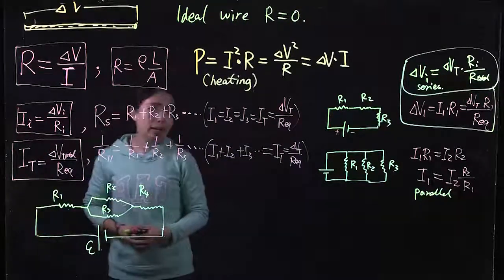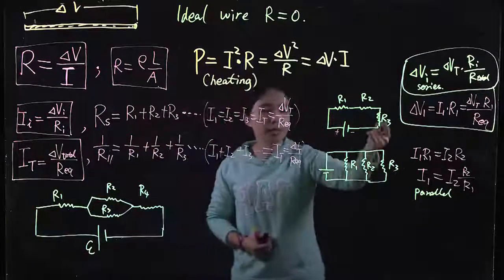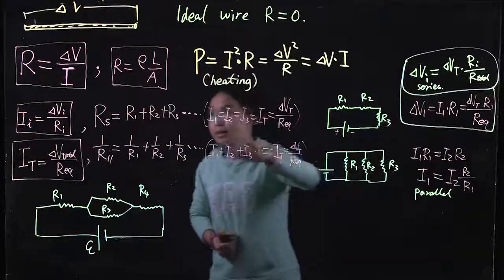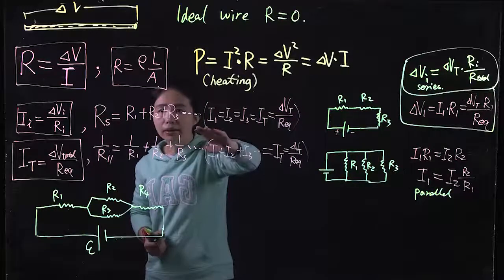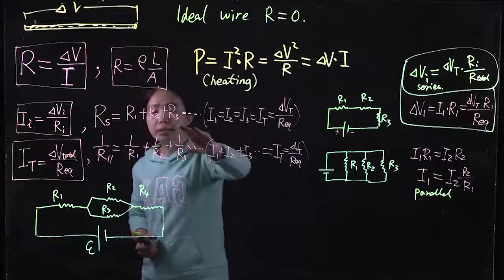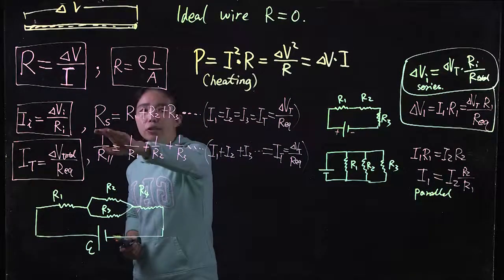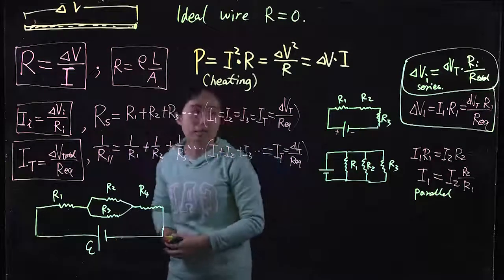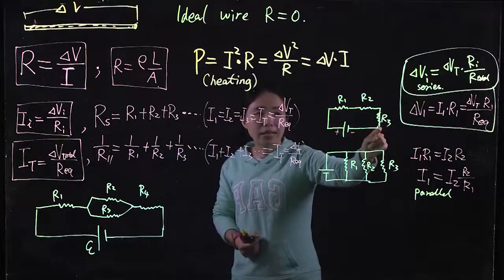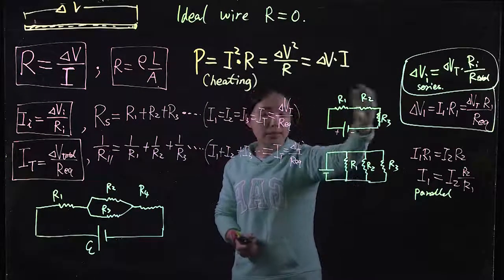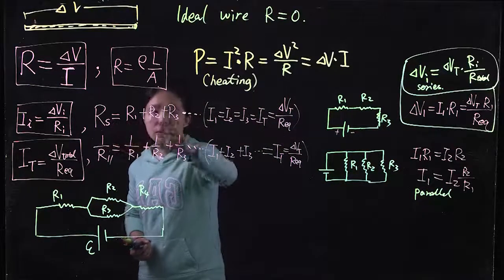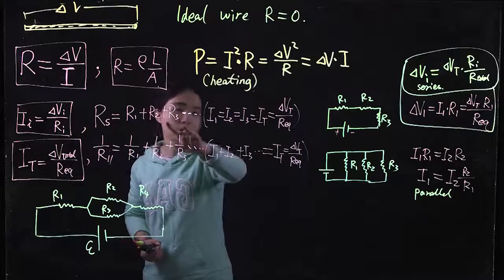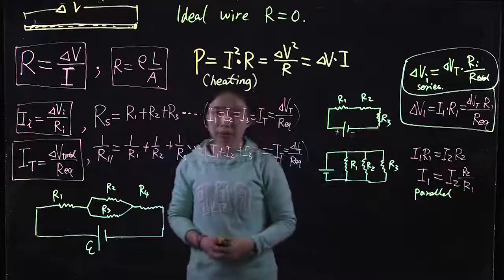And we know that if we have resistors in series, one after another, that's like adding and adding this journey, making it longer and longer. We're going to add the resistances together to give the total effective resistance. So three of them adding together is as if we have one resistor with a larger resistance equal to R1 plus R2 plus R3. You can add more, okay?